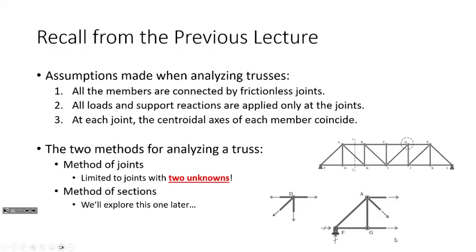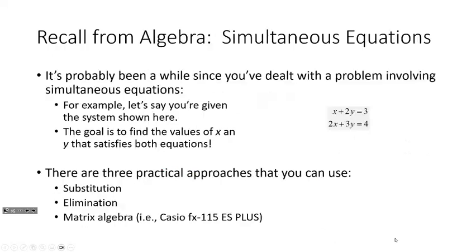I'm also going to show you today a little trick for making truss analysis a little easier. If you recall in my pre-recorded lecture, we had a truss that was a little bit more involved, but something happened that was kind of interesting for our very last member in that truss analysis. Remember what the force was in that very last member? 0. There was 0 force inside that member. And so one thing that you can do to speed up a truss analysis is to quickly identify members that contain 0 force. And there are ways to do that, and I want to show you that today.